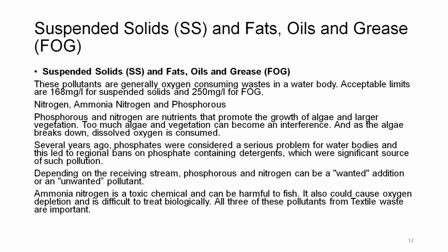Too much algae and vegetation can become an interference, and as the algae breaks down, dissolved oxygen is consumed. Several years ago, phosphates were considered a serious problem for water bodies, and this led to a regional ban on phosphate containing detergents, which was a significant source of such pollution. Depending on the receiving stream, the phosphorus and nitrogen can be a wanted addition or an unwanted pollutant.